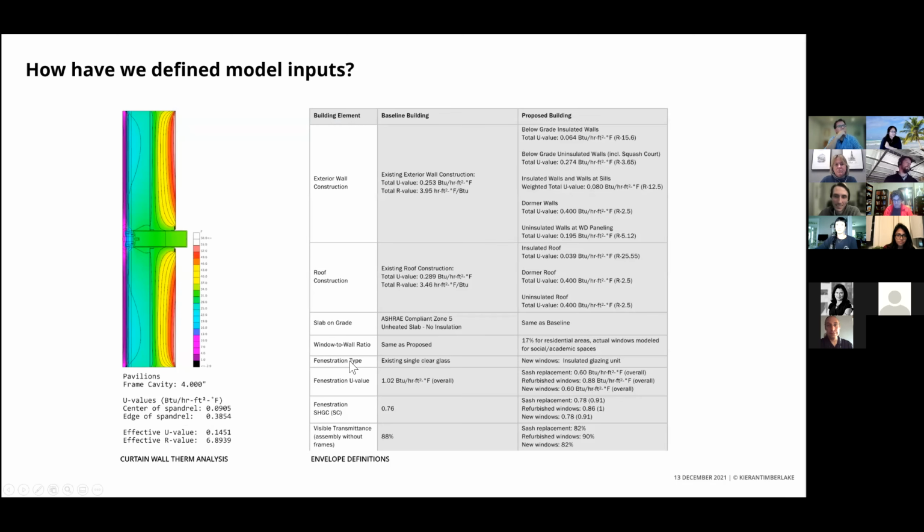All right, so other opportunities we find under the category of co-authoring are ways to go beyond assuming that each energy modeling surface is a uniformly applied U value or R value. I think everyone on the call understands the concept of thermal bridging, but whether that gets applied to energy modeling is a different question. So many code values may be expressed as either prescriptive R values or U values.